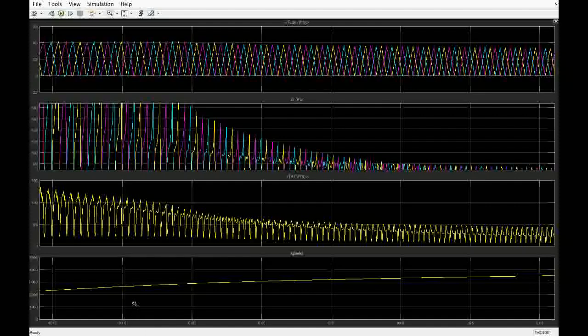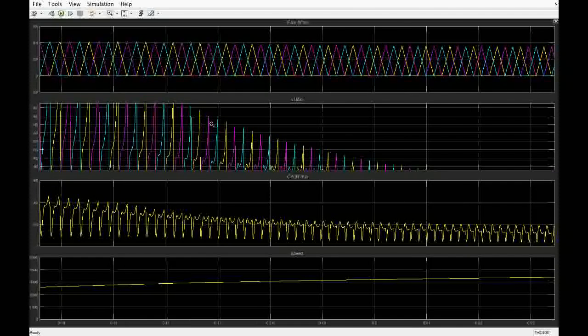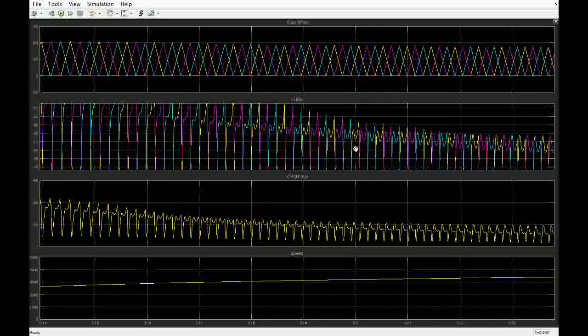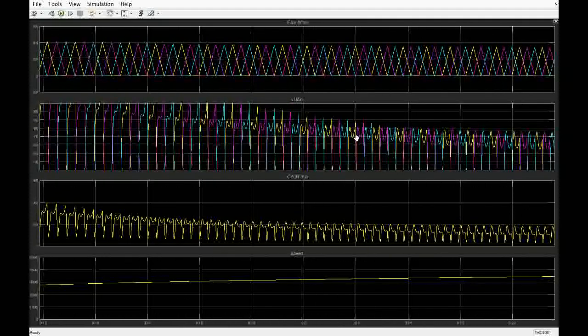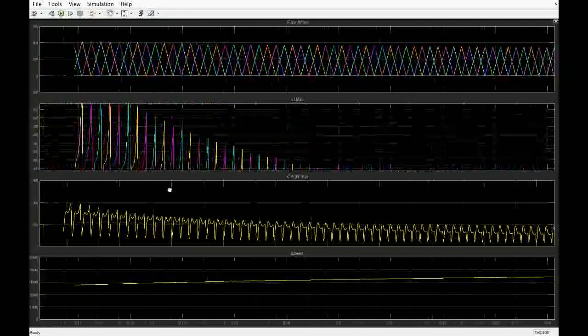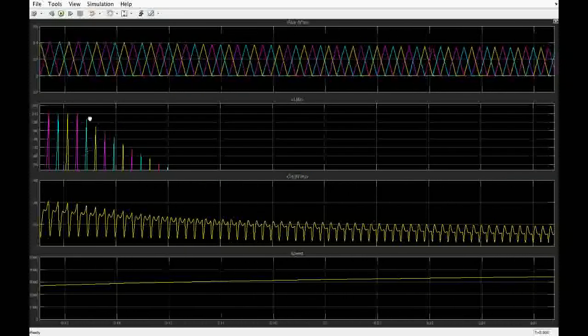So that happens after the speed reaches about 3000 RPM. So at that point, the motor excited is not current controlled anymore, because at speeds above 3000 RPM, stator currents do not reach the reference current anymore, and that's kind of why you see it decrease. So you see here it's about 100, 90, 80, and of course it doesn't exceed 200, because that's a reference current.